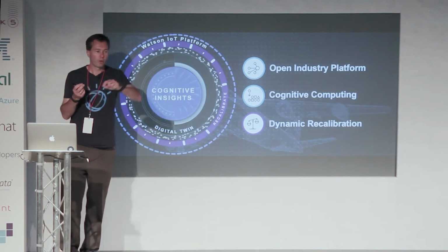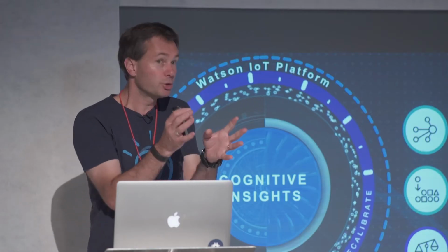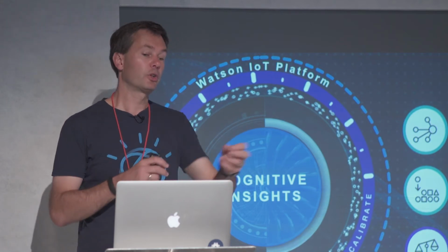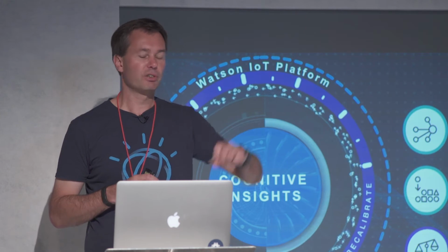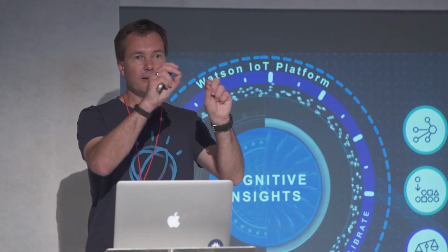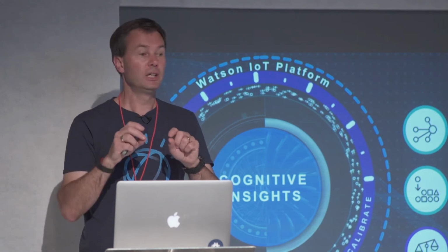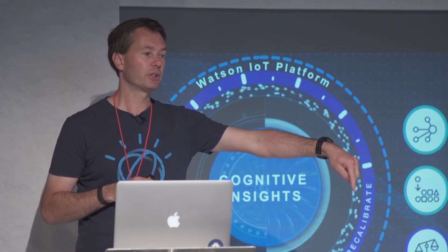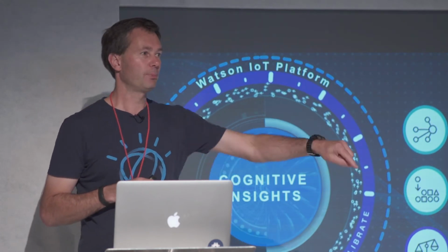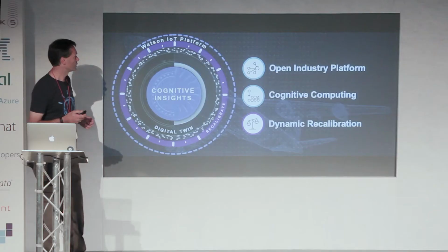So you say, of these 100 things, those two appear to be behaving differently. I don't know what's wrong with them, but they're just different. So you go and have a look at them and go, okay, yes, you're right, you spotted something there. There's a particular bearing running hot or something. So you then tag that feature in the data which says, if you see this, then the bearing is running hot. Next time that same feature appears in one of the other ones, you go, the bearing's running hot over there. Dispatch the right person with the right skills, the right parts in their van to go and fix it. So the system appears to have learned and become more intelligent.